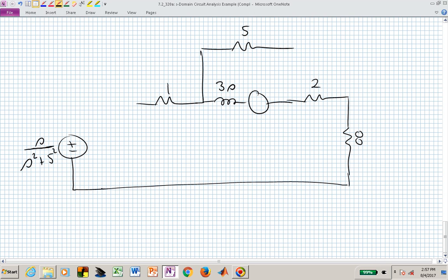In this particular case, we had a positive current from left to right, and we then know that the polarity is minus plus, with the magnitude being L times I sub L sub 2 of 0, so this is now 3 times minus 39 over 11.